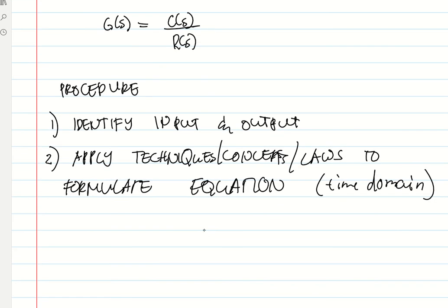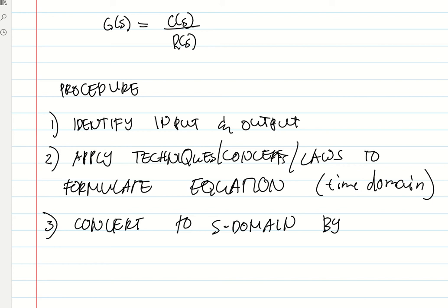Then after deriving the equation, you now have your equation based on the techniques that you want to use. We now need to convert that equation to the frequency domain or S domain by taking the Laplace transform.